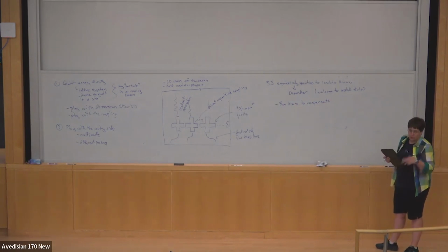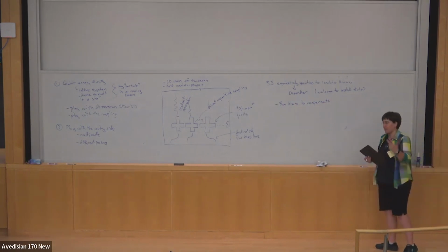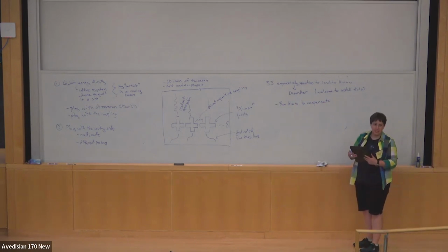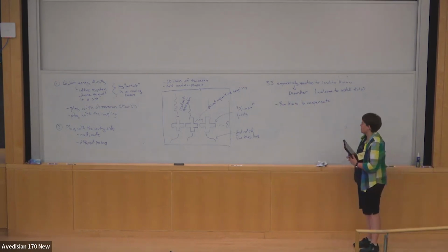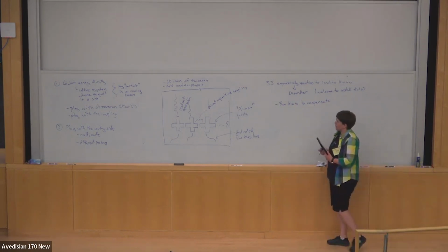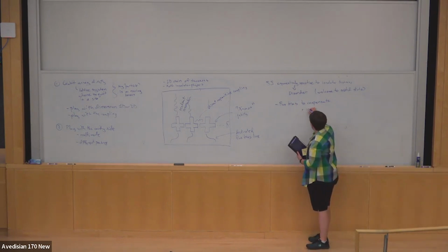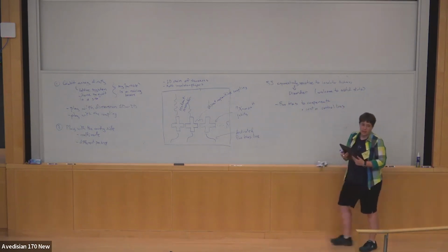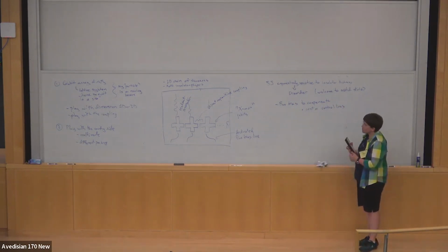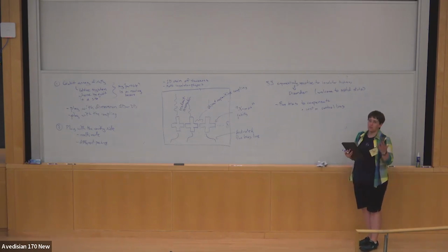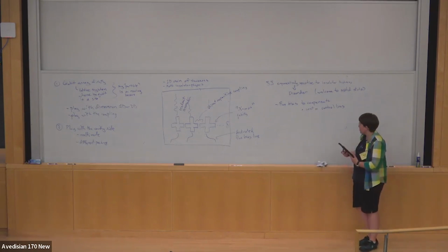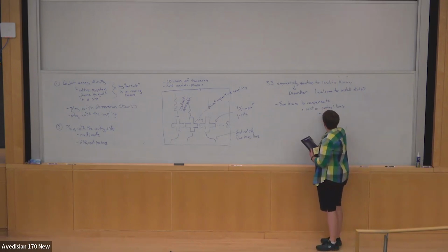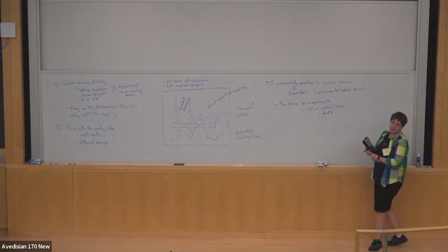And so you try to make all of the qubits the same, they don't turn out the same, and so then you have to individually tune the flux on each one to make them the same. And so you can do this, but it has a cost. So you need a whole bunch of control lines. And if you make your Josephson junction flux tunable, then it's sensitive to any other sources of flux besides you. And so you have control lines, and anything that's flux tunable then becomes sensitive to drift.